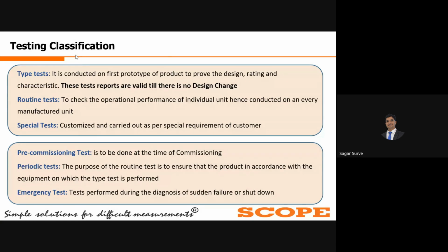So we conduct the routine test during the factory inspection whenever we have an order or are supplying the transformer. We conduct the routine test at the factory itself in the presence of the customer. At that time, if the customer asks for some special test also, that can also be conducted.